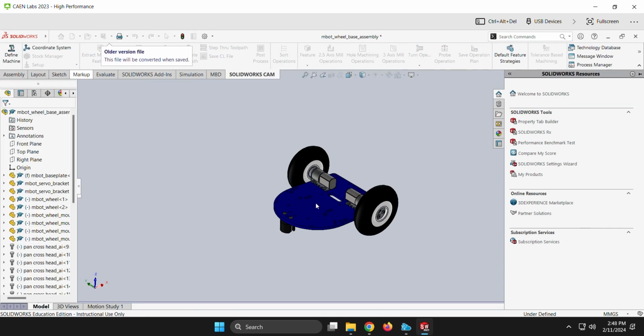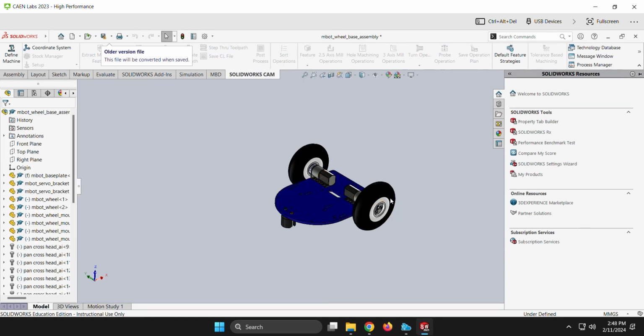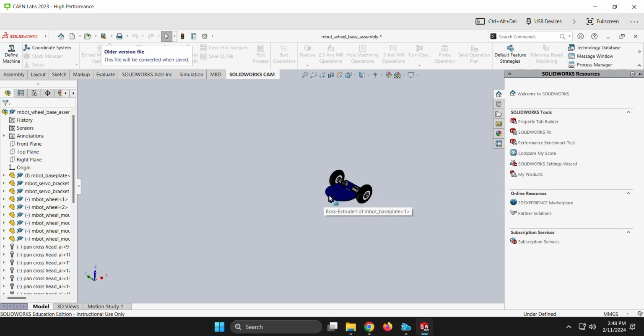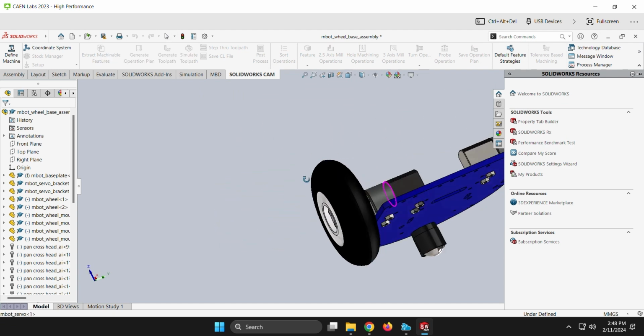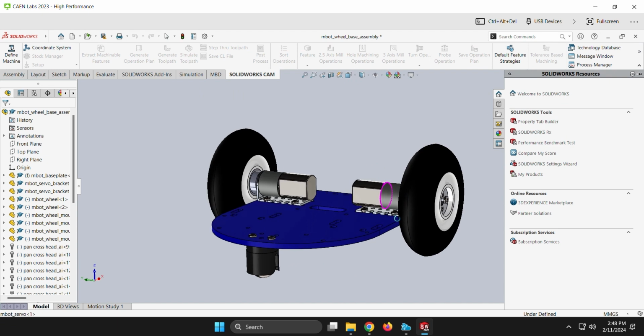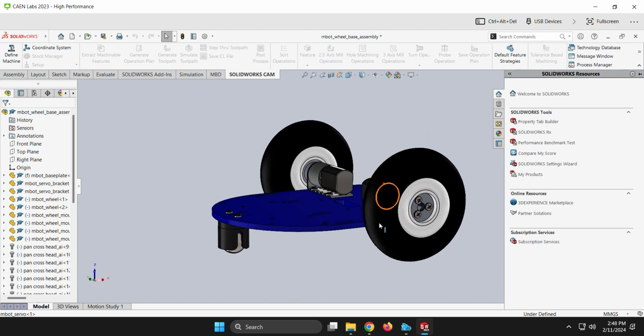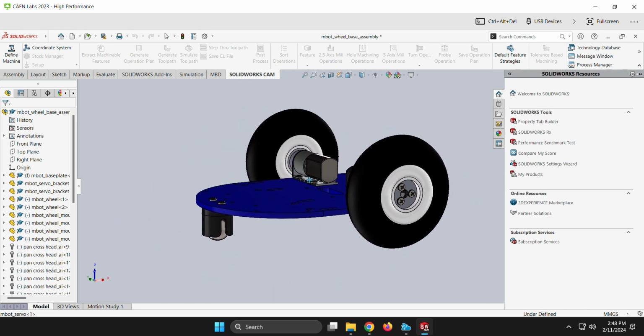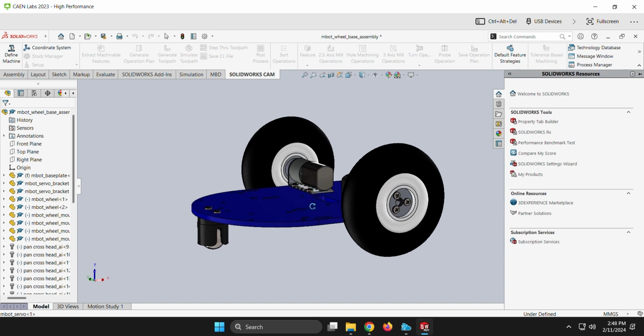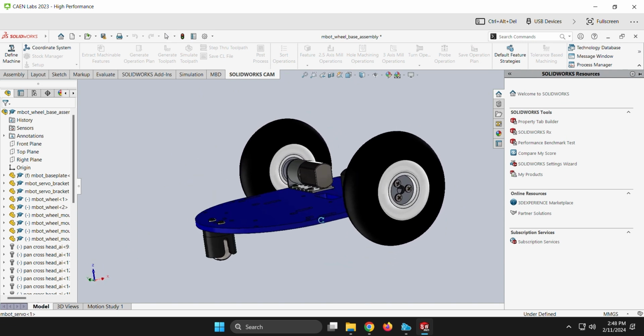First, we will go into some of the basics of how to orient yourself in SolidWorks. So first, you can use the scroll wheel to go in and out, like such. Sometimes it's inverted, and you'll have to decide what you like best. Next is rolling around. If you press down the center button of your mouse and move around, it'll rotate. Next, if you do Control and then the middle button, it will pan around, and you can move it on the screen to center it. And lastly is Alt and that middle button, and that will roll it around just slightly.